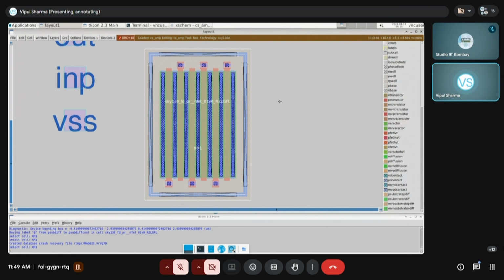But another issue which I see here is that the electrical connections from the gate to the local interconnect and metal one layer have been put on either side, on the top and the bottom, but I want all of them on one side, either the top side or the bottom side. The good thing about the Sky130 PDK is that all these features have been implemented inside the P cells.